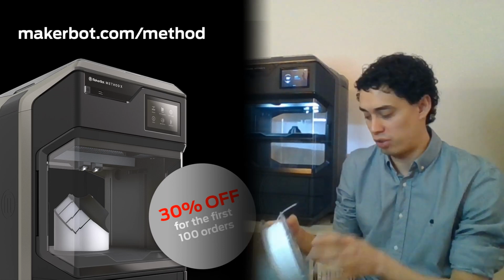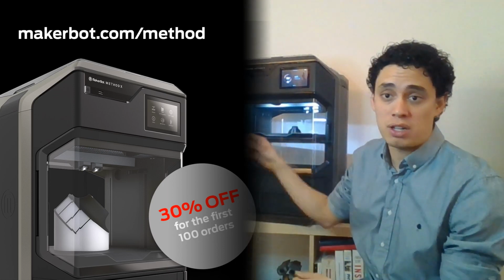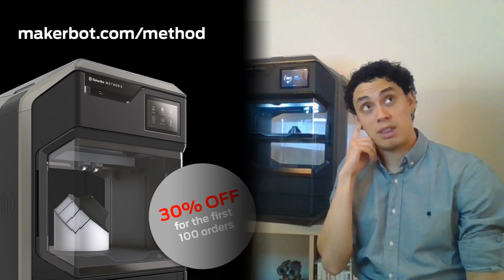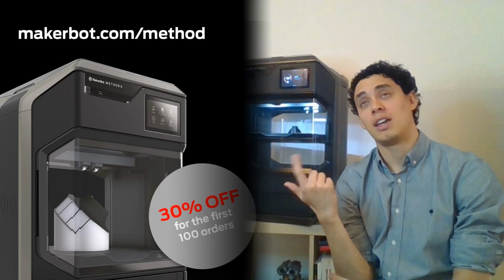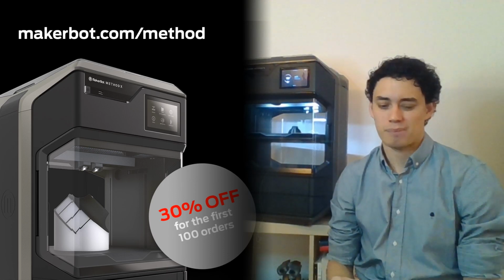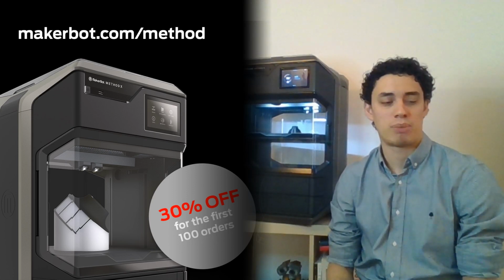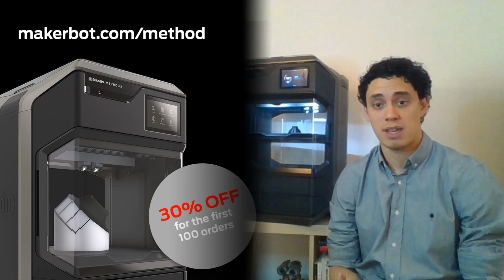And even the printing process is also not straightforward, because in this case, once the print is done, I just take the part out of the machine and wash it, and that's it. With the resin printer, first you have to wash it to remove the excess resin, then you have to cure it, and then I think that's it, and then you just clean it up. But still, in my experience, that's better suited for other applications, more specific ones. I really like FDM better. It's just a straightforward process.